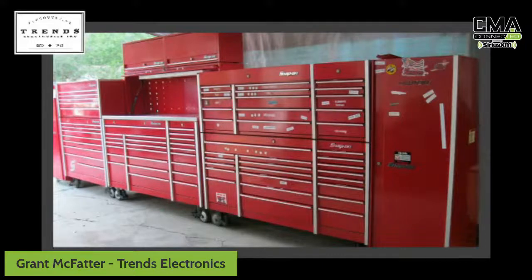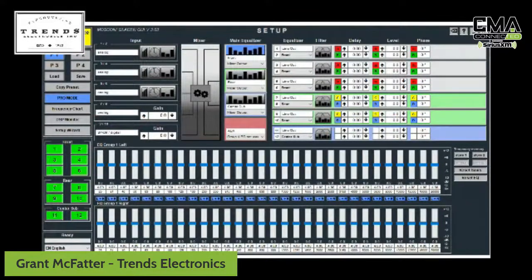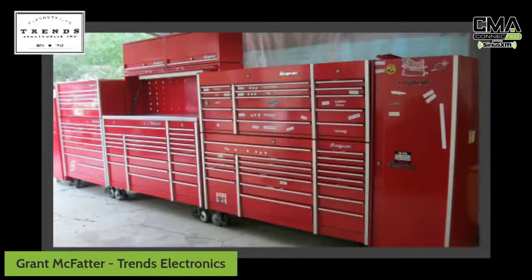Some dealers look at the previous screen and go, oh my God. And really all we need is a 10 mil socket set today. Maybe we start off with time alignment only. If you just did your crossover filter setup and time alignment, you would make a massive difference in your audio system. The EQ is what I think. But the time alignment is auto, and it's that really specific tool you need called a tape measure. God forbid we know how to use a tape measure, right? And click in 36 centimeters on a box. But again, this was the quick graphical representation I could think of. You've got this massive toolbox, and you need a 10 mil socket set to get this job done.